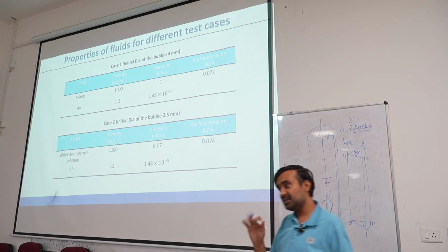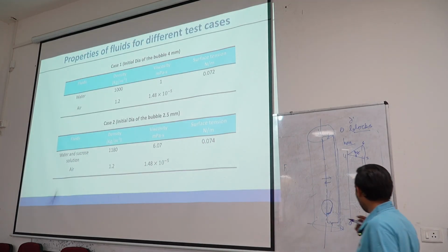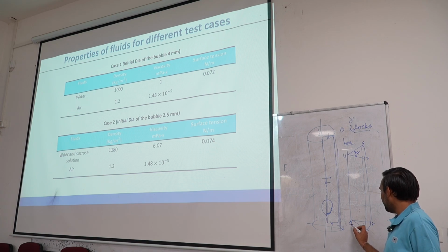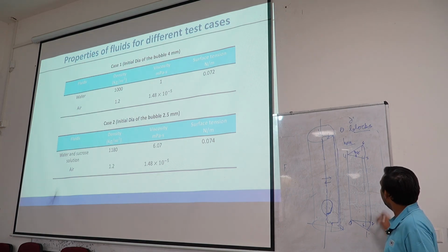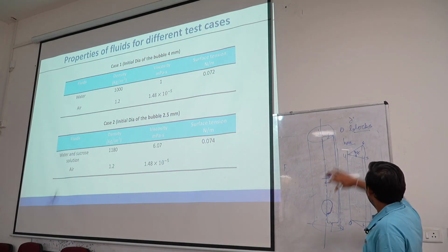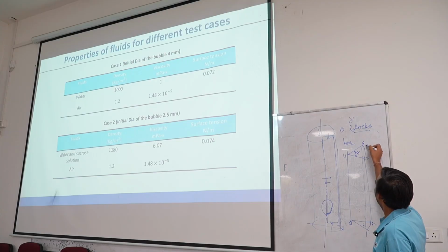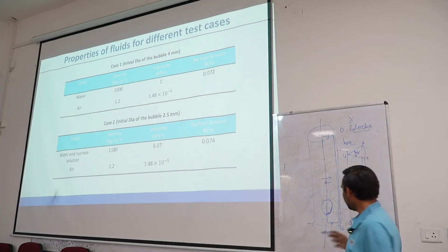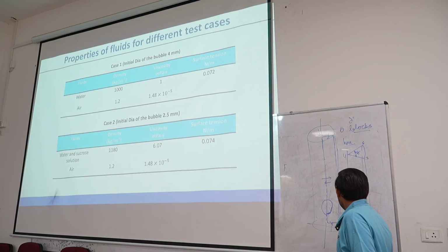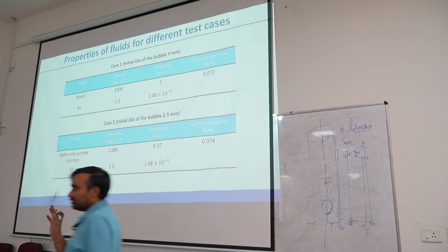So, I have only 6 vertices, but for the hexahedra to form, first I can give the indices as 0, 1, 3, 4, which will be taking the front face. Then for the back face, I can take 0, 2, 5, 4. In this case, these origin points on the axis will be common.